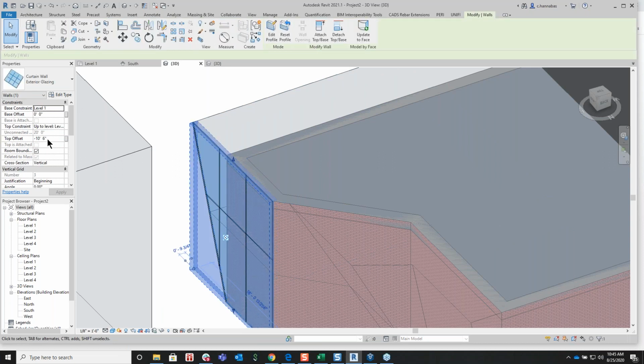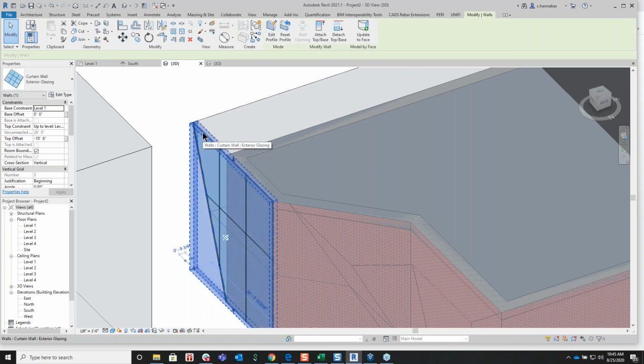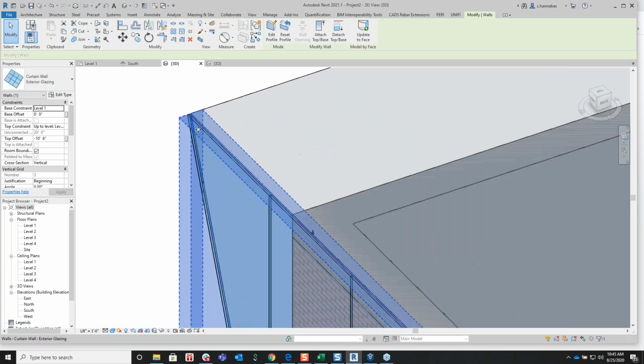Now you have a curtain wall and you go through. Now, what I've done in the past in curtain walls is I can go ahead and start adding in my beams and braces across these. A lot of it depends on what you're trying to accomplish, what your level of detail is. What I've done previously is whenever I cut a section through a curtain wall, I actually built the detail inside the curtain wall. So when I cut it, I could actually see all the bracing, how all the mullions are shaped, everything like this.